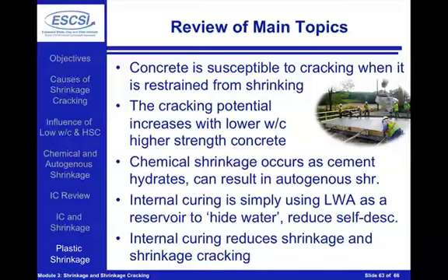So if we can take a second to review, what we really want to do here is review the main things that we've seen in Module 3, which was focused on shrinkage and shrinkage cracking. The idea here is that concrete can be susceptible to cracking when it's restrained from shrinking freely. The cracking potential can increase with lower water to cement ratio, higher strength concretes. The main reason for this is because we're going to have more autogenous shrinkage taking place in these cases.